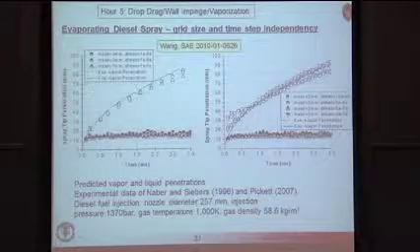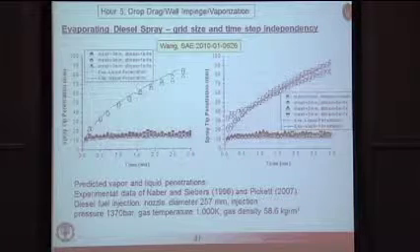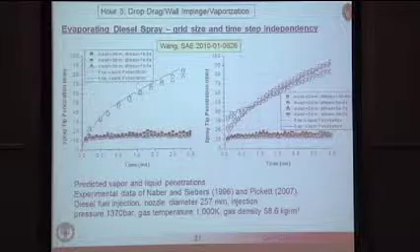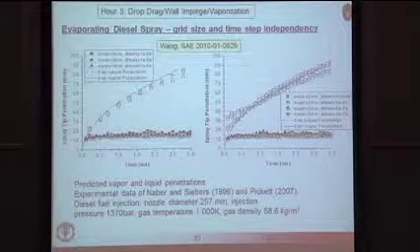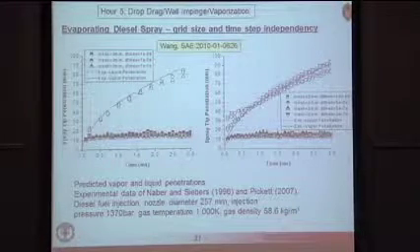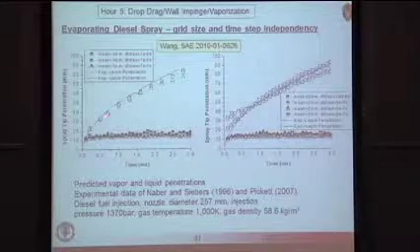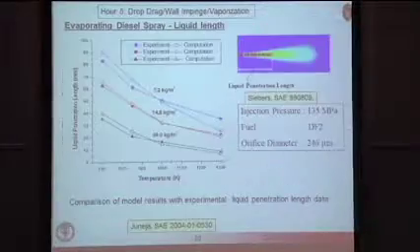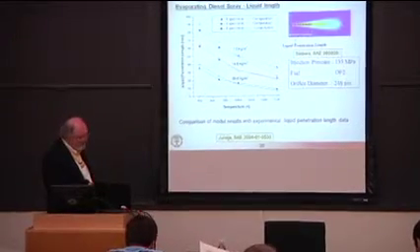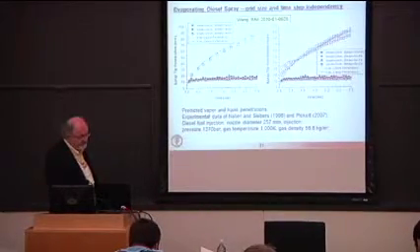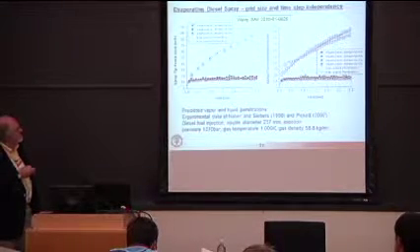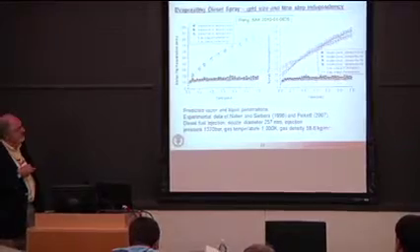We, again, have looked at the effect of mesh resolution on results like this. Here you see changes in mesh size from 1 to 3 millimeters. In this case, we're keeping the time steps, again, around 1 microsecond. This shows the vapor penetration, in other words, the distance from the nozzle to the tip of the vapor jet. And the other shows the liquid penetration. That's this data down here. And somewhere buried inside all this is the experimental data, but it agrees quite well.